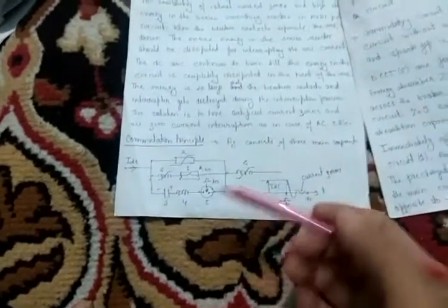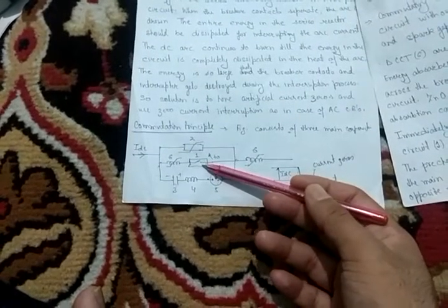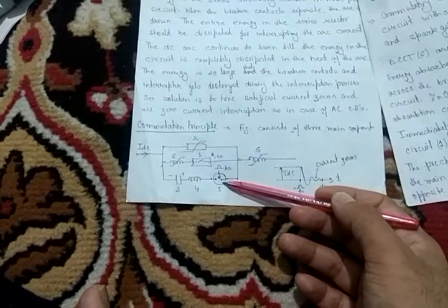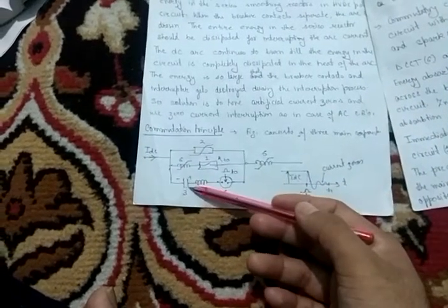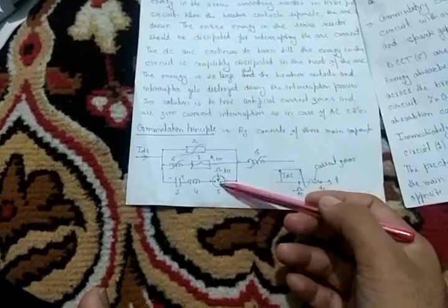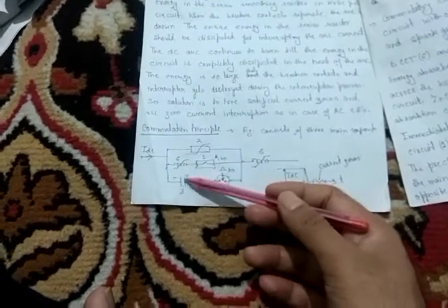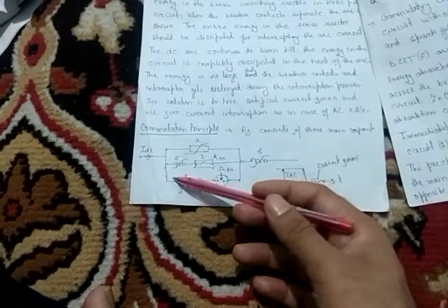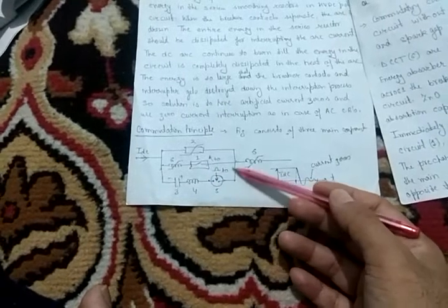So what is happening? Immediately after opening the contacts of the main breaker, circuit 1, this vacuum gap triggers at time t equal to t naught. The moment it triggers, it is a short circuit. At that time this side will be positive and this will be negative, and the pre-charged capacitor will discharge through this path.